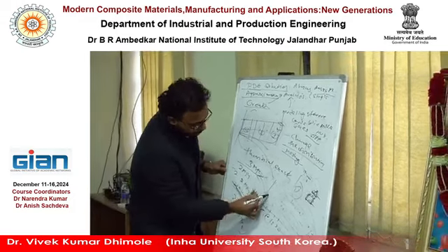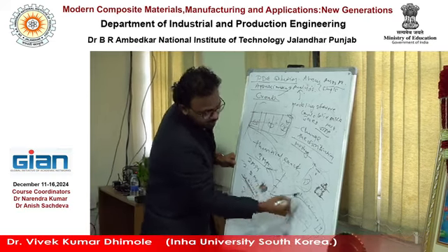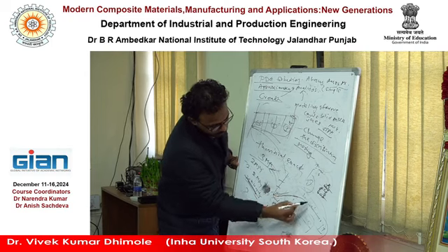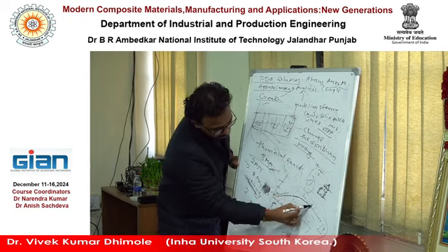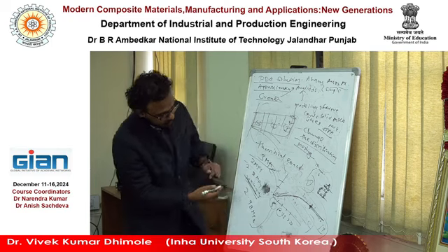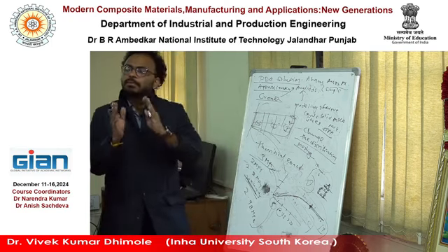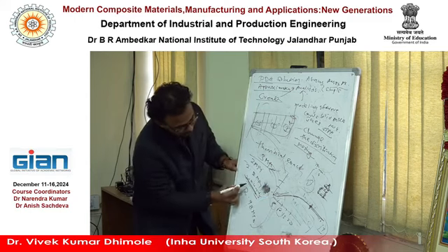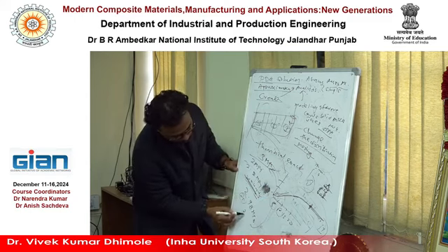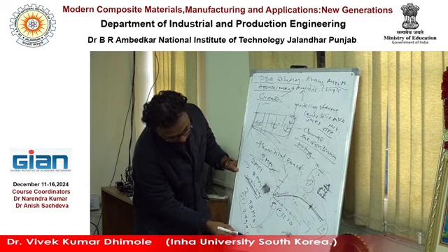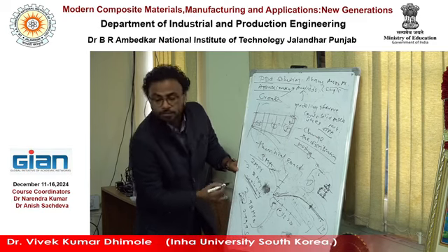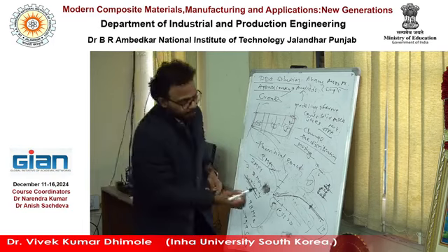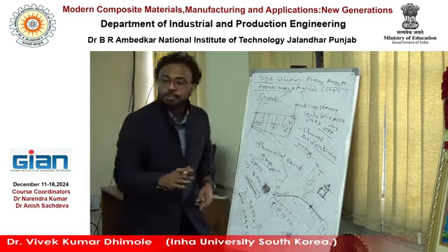So there is a stress value, and you can reach here, then it will stagnate. Up to here the solution is going toward the accurate value. After some point, however many elements you increase, it will give you the same result. So it will stagnate, right? Suppose 25 elements give you exactly 2.99995 megapascal. So it is your stagnation point, 25 elements. If you increase to 30, 35, it is approximately the same. Maybe sometimes it can go down or up, but it will be approximately the same.